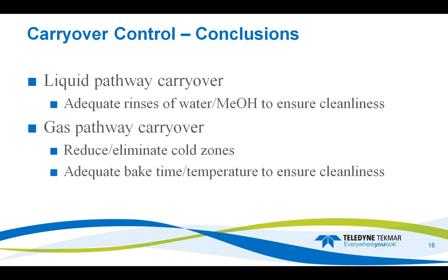Also, on the gas side of things, we want to make sure that we reduce or eliminate our cold spots. And then again, make sure we optimize our bake times, our bake flow rates, and our temperatures to ensure cleanliness. But also possibly reducing those times if we have them set too long. So finding that nice sweet spot where we can get adequate cleanup but not extend our runtime so much that we start losing productivity.